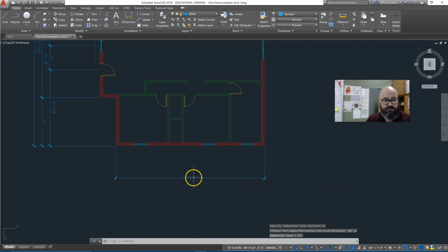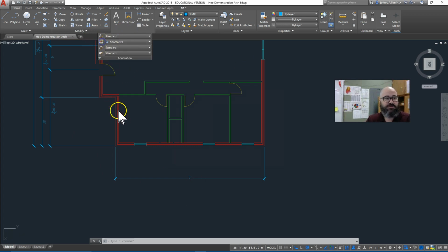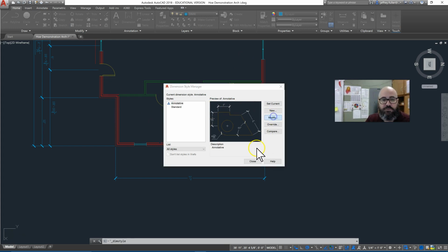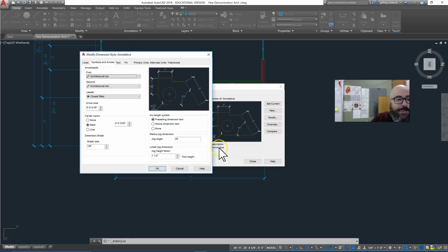One other thing I want to do is change my numbers. I don't know why this one shows up like it is here, where all my numbers are above the dimension line. See, all the dimensions that I'm measuring sit above the actual dimension line that they refer to. This one is in the middle, and it is also switched around to the side. So let me go in here and check, see if I can figure out why it's doing that. We'll go to modify, and somewhere, see here, above dimension text.